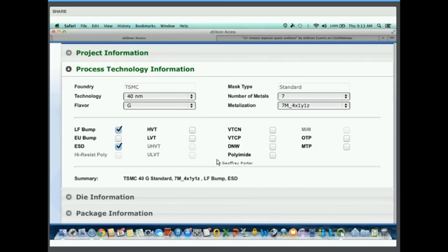All right. And we'll manage our power by using the high voltage threshold. Okay. And we will still need low voltage to get the critical speed pass done. So let's select that as well. And then for our cores, we'll need optional VTs for the N and P device. Yes, so those two would be perfect.